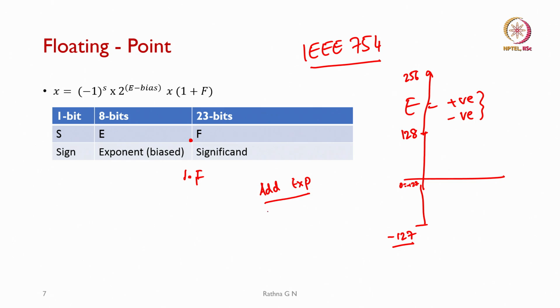Whereas for addition, if you are adding two numbers, you have to bring them to the same exponent and then add them up. So, the 6713 is a floating point processor, which takes approximately, if it has to do maximum adjustment, 10 clock cycles to do addition.